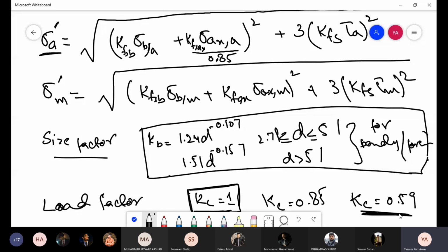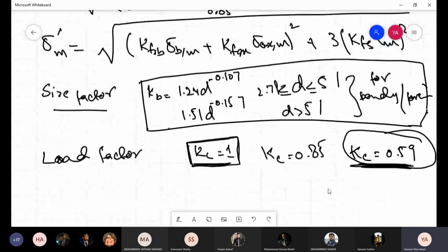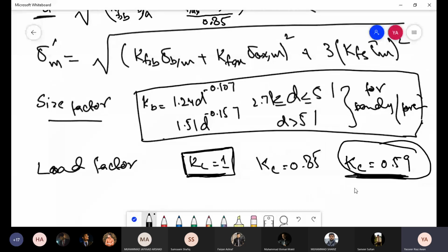Okay? This we don't need to consider for torsion because in combined loading, the von Mises stress basically has an inbuilt factor for taking care of torsion. We have previously seen that when we do the pure torsion case through distortion energy, it gives you 0.577 of the yield strength, okay. So that 0.577 factor is inbuilt into this equation, okay.